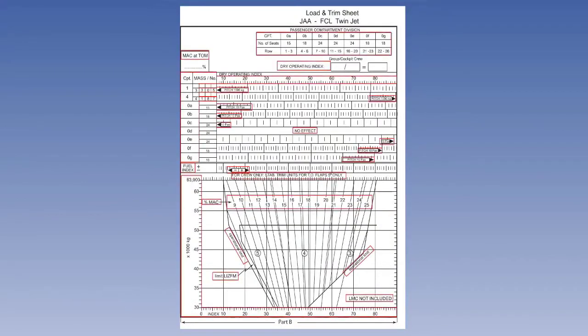Having completed the medium-range jet transport load sheet, Part A, we will now input the appropriate data into the trim sheet, Part B, which deals with the distribution and trim positions. This will enable the pilot to establish the zero fuel mass and takeoff mass centre of gravity position, expressed as percentage mean aerodynamic chord, for the combination of passengers, cargo and fuel load. The landing mass centre of gravity position is seldom required because it will remain within limits due to the fuel usage during the flight.